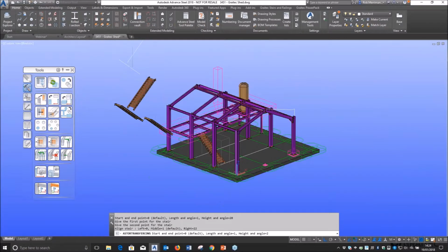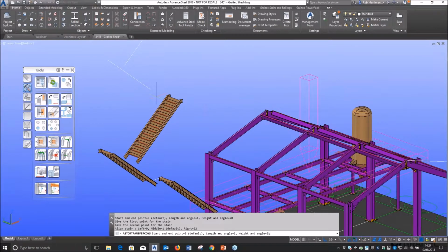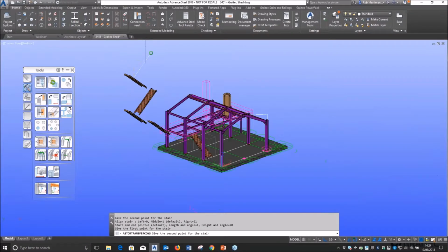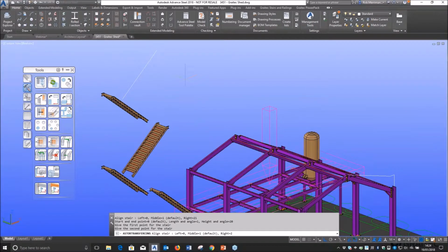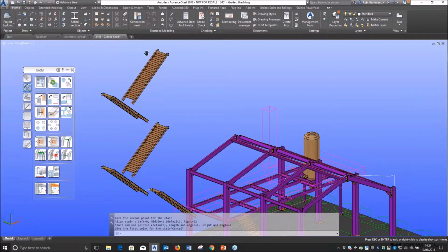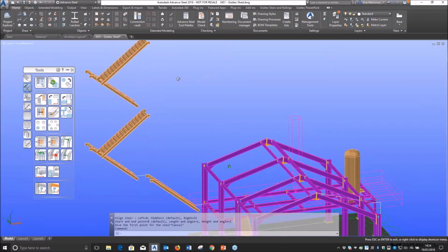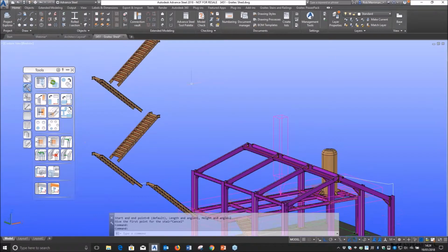So if you spend the time putting your construction lines in, using the stair macro and the joint copy feature, you can populate your entire model with staircases very quickly. And those are all separate joints now, so if I did have different landing configurations or different tread configurations on each flight, I can go in and change those.